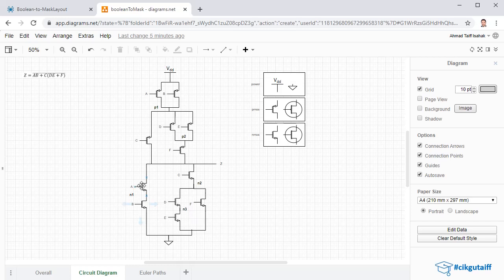So basically in our Verilog, we define each and every one of these transistors in the drain, source, gate order, where drain, source, gate refers to the particular node label. So for example, if I want to model this PMOS transistor for signal A, then my code would be something like PMOS space and then maybe some kind of device name, for example, P01, and then brackets.